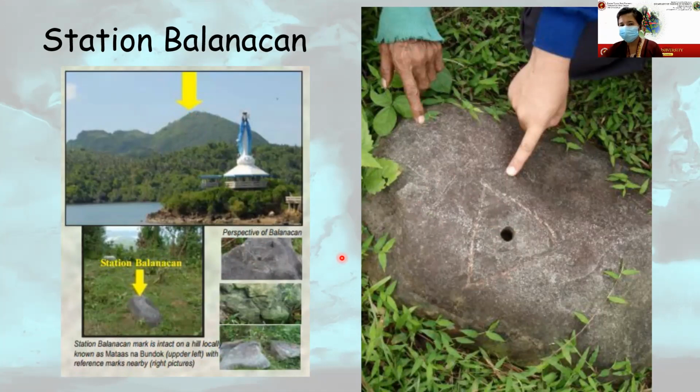So in the Philippines, the reference ellipsoid, which is the Clark 1866 ellipsoid, fits to this portion. So this is now the initial datum of the Philippines. We are using this as our mother reference system. This is being realized as a system and being established.